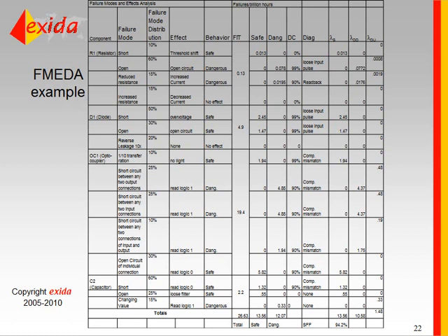And so 94.2%, if it's a SIL 2 product, that will say you can use that. It's related to redundancy, or what they call hardware fault tolerance. You can use that for SIL 3 in a redundant system at 94.2%, and you can use it in a non-redundant system for SIL 2 with that safe failure fraction. So there are essentially tables in the standard that relate the safe failure fraction to the level of redundancy that you need.